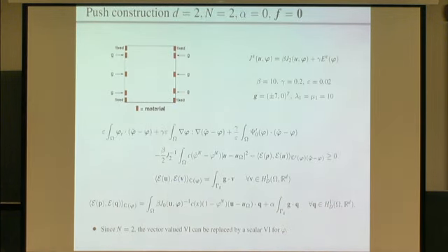And then finally, here we're taking alpha equal to 0, and we want to try and minimize the L2 error between our displacement and the objective displacement that we're looking for. As I say, we want U to be 0. We want the displacement to be as small as possible in the whole of the domain. In this case it's 2 space dimensions. Again, it's just single material. It's not multi-material. We're just dividing the domain up into material or void.